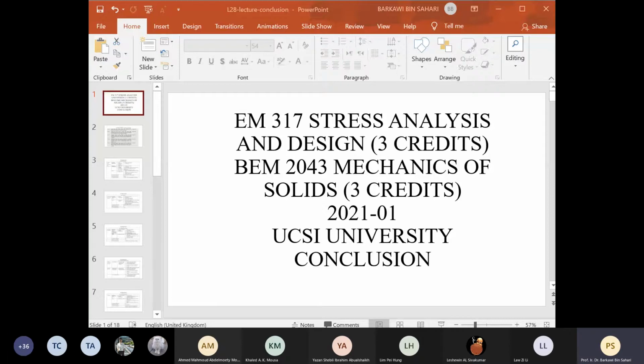For example, for the tube inside a tube, I can't remember which question. If you cut, you can put tension as positive in the free body diagram, and it is consistent throughout. And at the end of the day, you got the answer for that particular stress is negative, which is opposite to the initially assumed direction. Then the actual one is in compression, that kind of thing. So if it's consistently carried out, then it should come out with the right numerical answer.